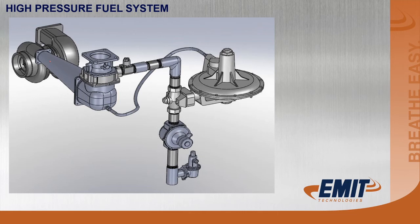A high pressure fuel system typically has a turbo boost going into the mixer, and then this would be going to the engine intake manifold. The part we're concerned about on this is what should our fuel pressure be. This is where we always want to check fuel over air. So we would have a test port in here somewhere, and we'd have a test port on this housing, and we would measure our differential between the two.